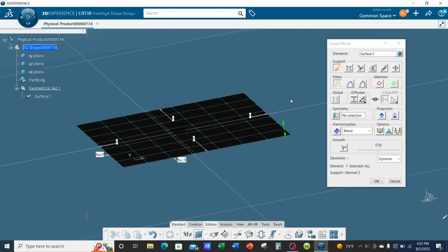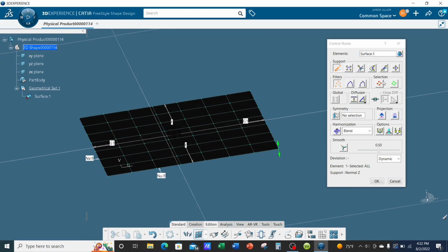All right, so let's increase from F to G0 to G1, tangent continuity. Let's do it on the same two opposite sides. G1, tangent continuity. Let's see what happens when I select all points again and go in the Z direction.